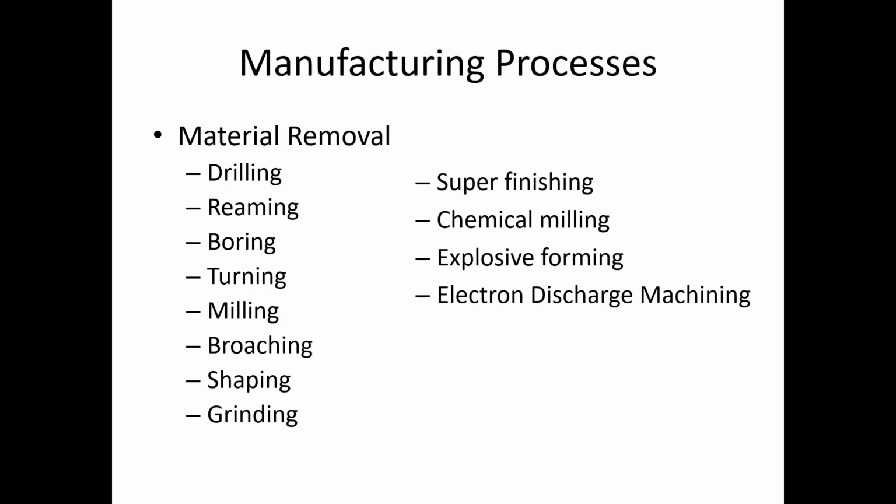So your standard drill off the shelf has got some rough tolerances, right? So if you really need a precision hole, then you would pre-drill a hole and then ream that hole to the precise size. You'd pre-drill it undersized, and then the reams are only designed to cut a small variation. Usually they're paired with a certain drill, and then that ream would take out the rest of the material to a very precise size. Similar tool, but a much more precise tool. Usually it doesn't have a point on it because it has to go through a hole that's already there. So they're usually flats.